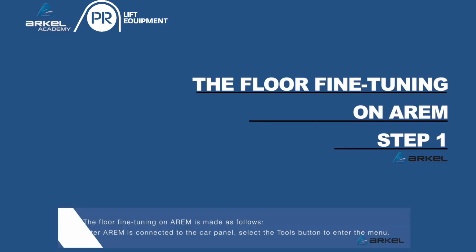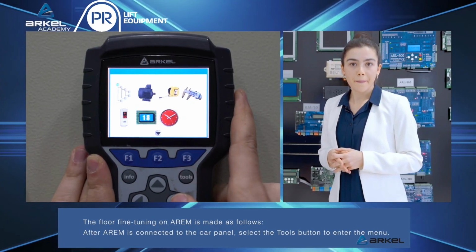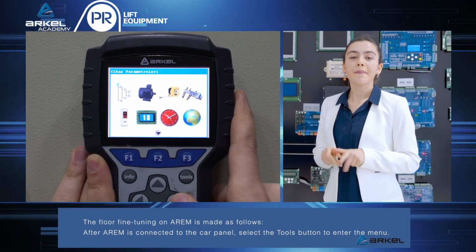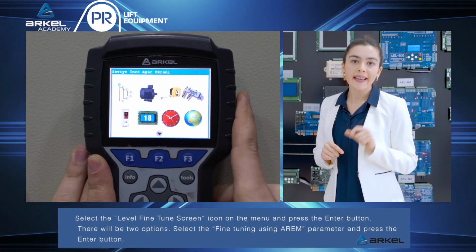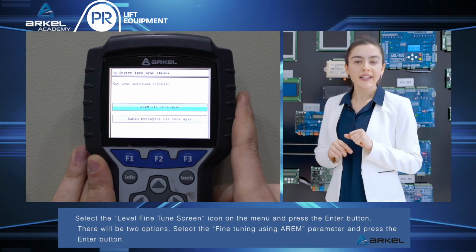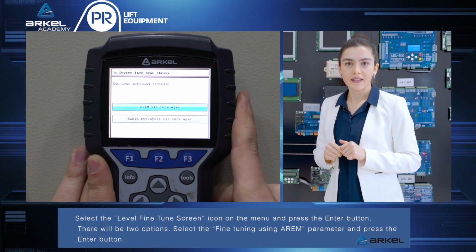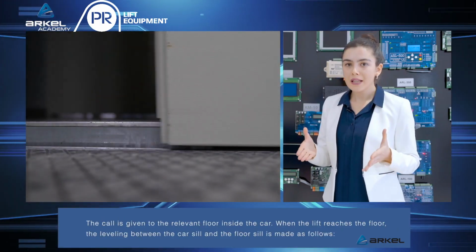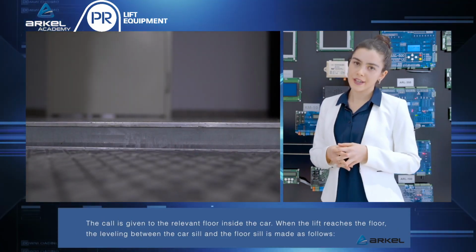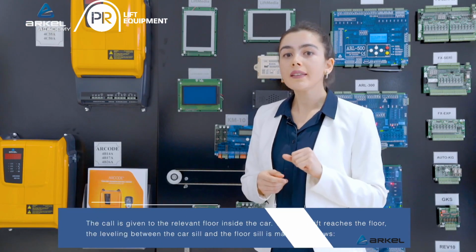The floor fine-tuning on RM is made as follows. After RM is connected to the car panel, select the Tools button to enter the menu. Select the Level Fine-Tune screen icon on the menu and press the Enter button. There will be two options. Select the Fine-Tuning using RM parameter and press the Enter button. The call is given to the relevant floor inside the car. When the lift reaches the floor, the leveling between the car sill and the floor sill is made as follows.